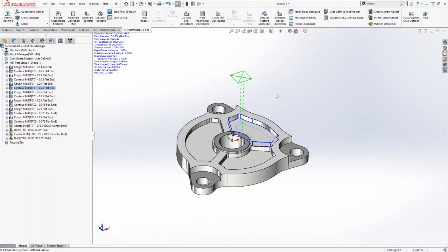So the difference between Visualize Standard and Visualize Professional, the main one is that Visualize Professional can do animations. So it can render out animations. It has its own animation wizard. And Visualize Professional can also do custom lights, point light creation, spotlight creation, things like that. Whereas in Visualize Standard, you're mostly using the HDRI background to handle the lighting. So it's a good point, though. We should definitely do a video comparing Visualize Standard to Visualize Professional. And if we don't have one up, then I'll see that someone gets around to that. Might be me.